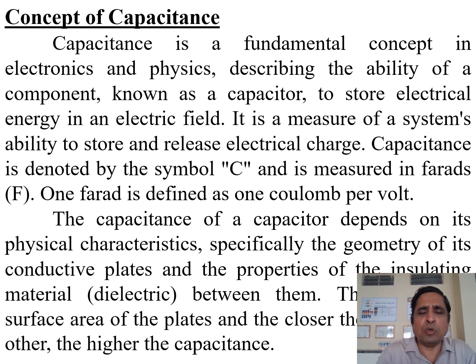So as we know, the capacitor is a very important electrical device. It is used for storing the energy and it has got different applications that we will discuss afterwards. So the capacitor is basically two parallel plates separated by dielectric material in between them. The dielectric material can be air, mica, paper, glass. So any insulating material can be used as dielectric media in between these two.